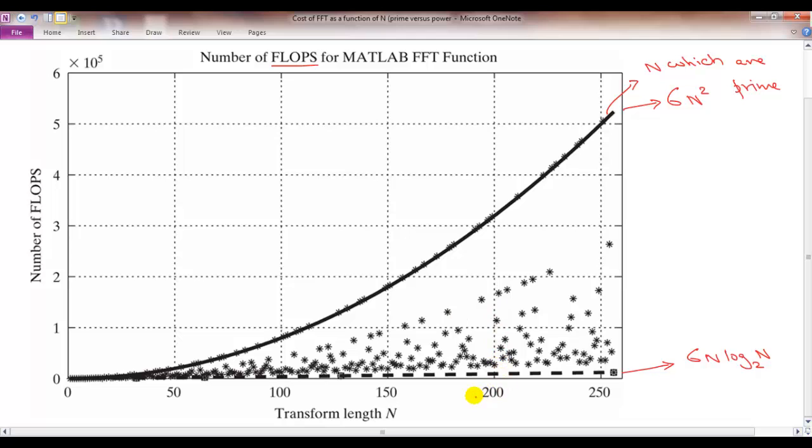So just doing FFT is not enough. If you just take MATLAB FFT and say, I'm using FFT, I should get good performance, that's not going to work till you really focus on giving it a power of 2 sequence. Okay, you either zero pad it or you make it a power of 2. You work with power of 2 sequences. If you don't do that, then as this plot shows, if you work with prime n's, you might as well just be using the explicit formula. You don't even have to use FFT. Okay, so this is just a plot from your book. You can read more about it.